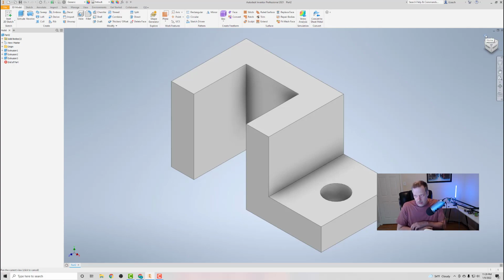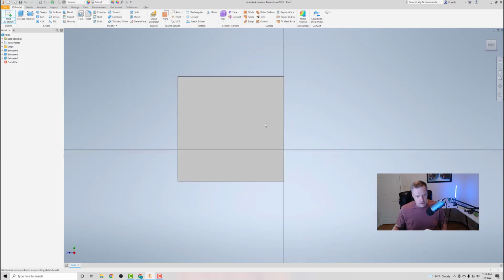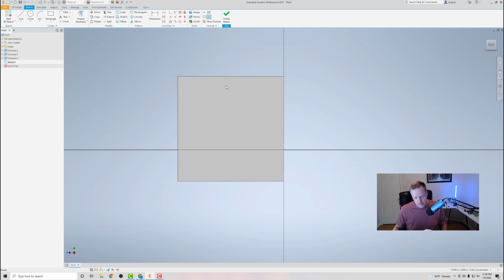And now we're going to add another cut. Okay, I'm going to add another cut feature. So basically I'm going to create a triangle, it looks like. I'm going to do a start 2D sketch. I'm going to click this face here. Start at the upper left corner and create 3 line segments to form a triangle. Do not align the endpoints to the midpoint, and so on.